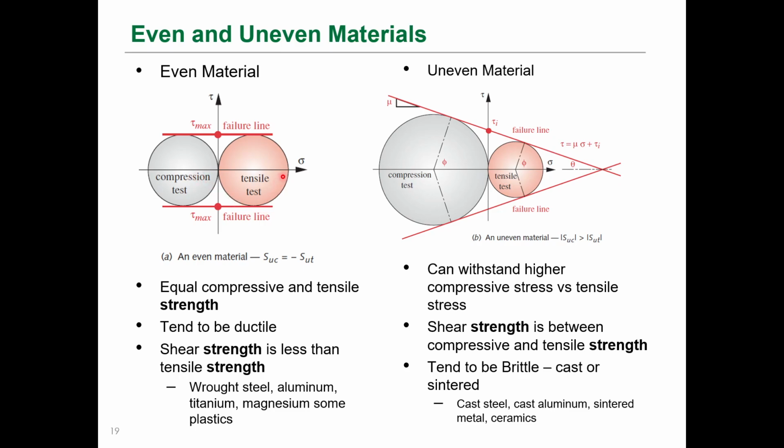Okay, and so these are your Mohr's circles, and you had Mohr's circle in your materials class, but this is your stress axis here. Your principal stress axis, and then this is your normal stress, and this is your shear stress.